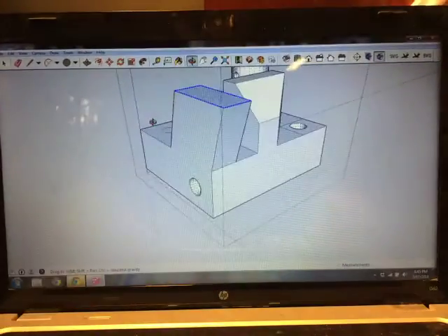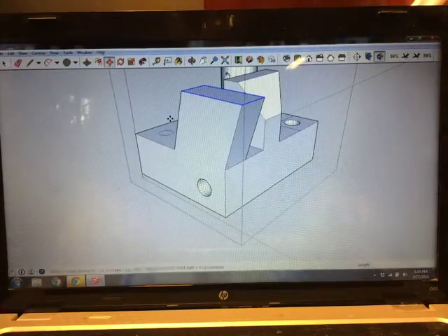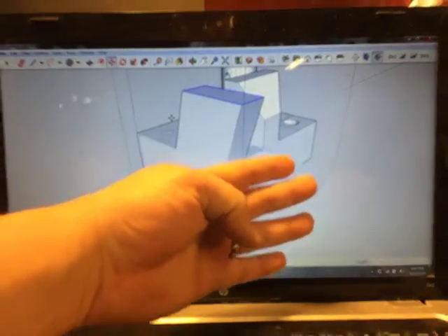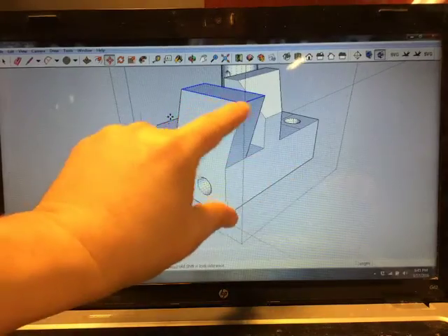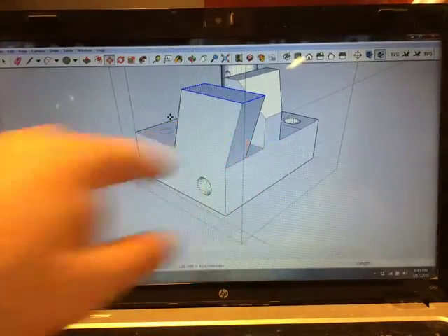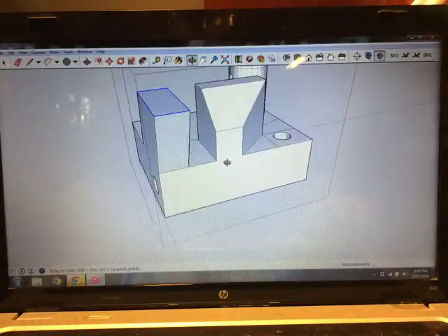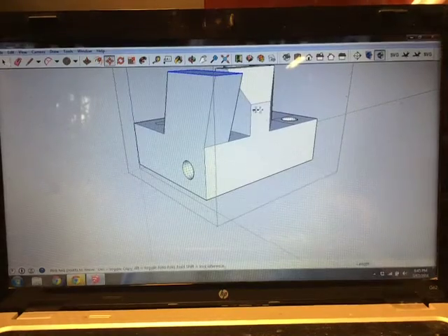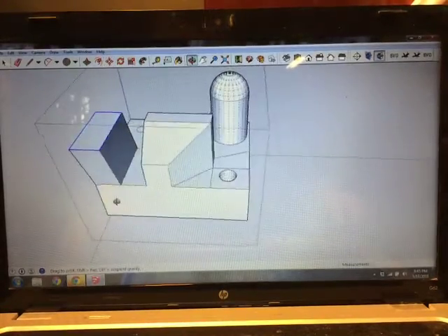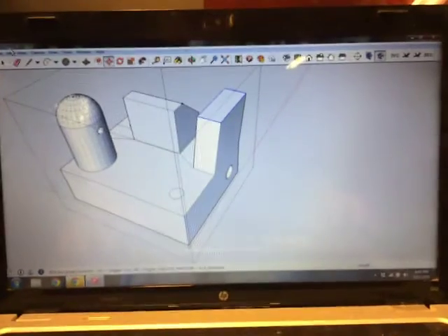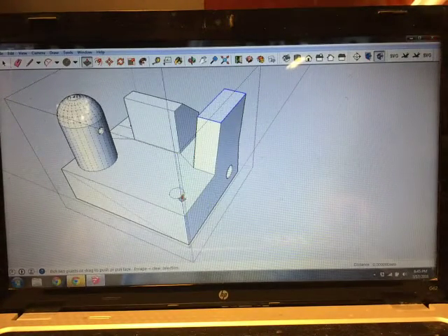Now, hopefully you guys saw that. I had to put a crease there. SketchUp will sometimes do that, but sometimes it will try to fold the whole surface, but if there are too many of these points that it just doesn't have the liberty to move this line, then you have to create fold points.